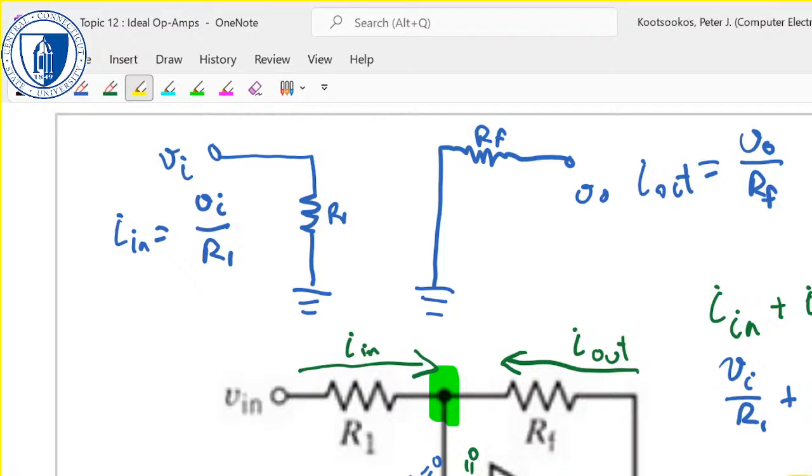There are better. They're still op amps. There are op amps designed specifically for audio. But again, the design, the analysis is done exactly the same way. They're just a triangle with a minus input, a plus input, and an output. The real devices have those slew rates and saturation voltages and currents.